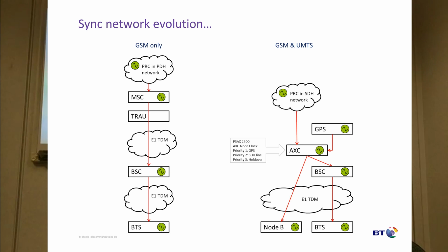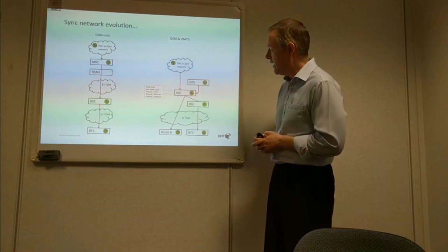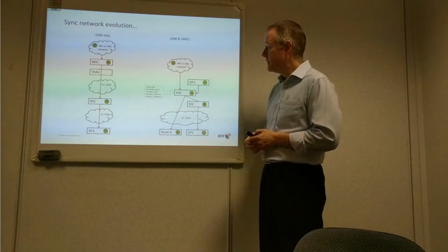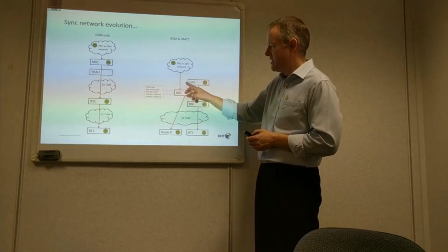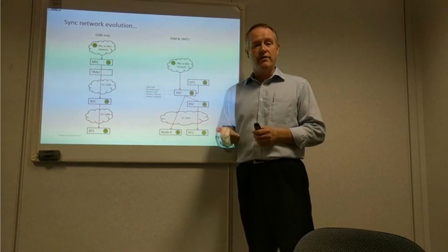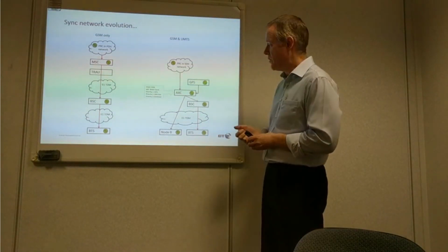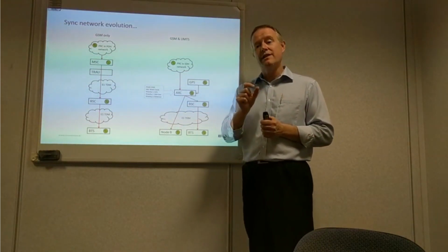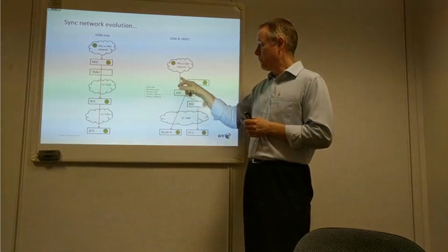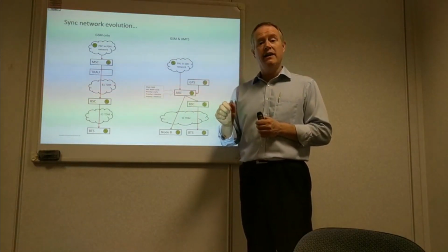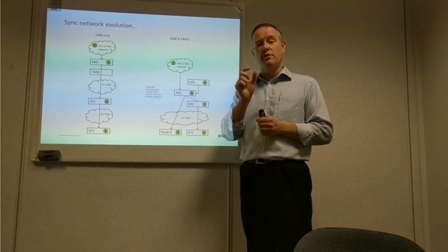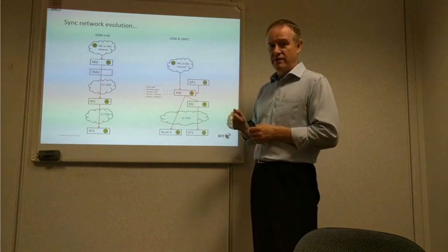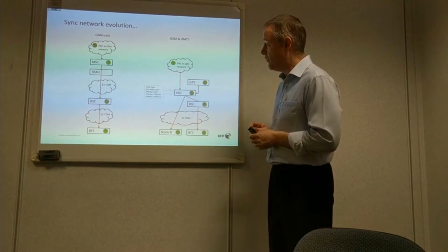We've now got primary reference clock in the SDH network here. We need to connect to an ATM cross connect. But actually quite often this SDH transmission here was delivered by a third party. So there's no guarantee of the performance on that. And particularly E1s carried within a transmission line were actually susceptible to pointer adjustments as well. So even though we're going to recover the E1s eventually, there's no guarantee of the synchronisation performance.